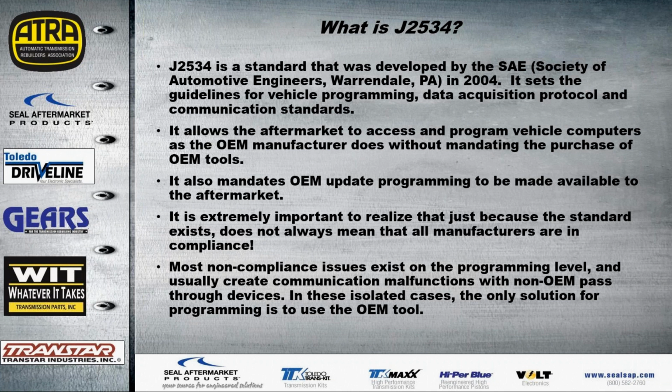What is J2534? J2534 is a standard that was developed by SAE, the Society of Automotive Engineers, in 2004. Basically what it does is it allows us, the aftermarket, to obtain OEM programming and download that programming and then utilize non-OEM hardware to actually upload that information into vehicles to solve shifting and other concerns that may need to be addressed on the powertrain.